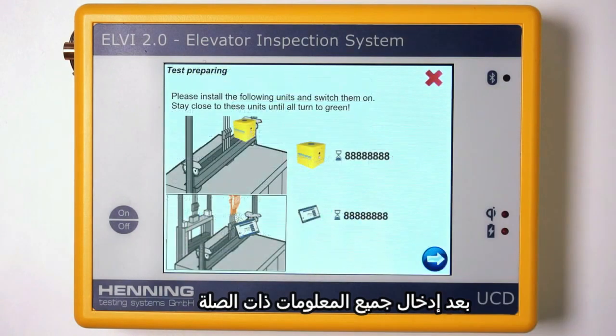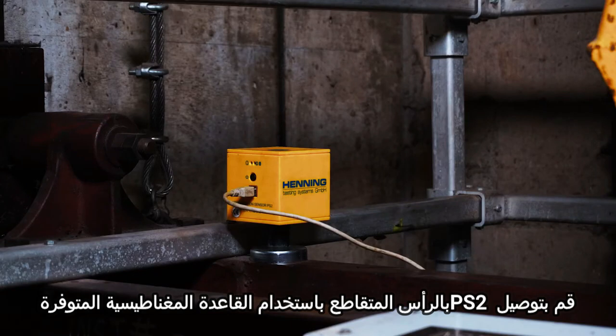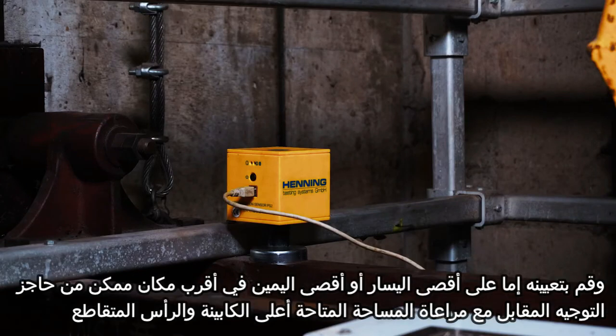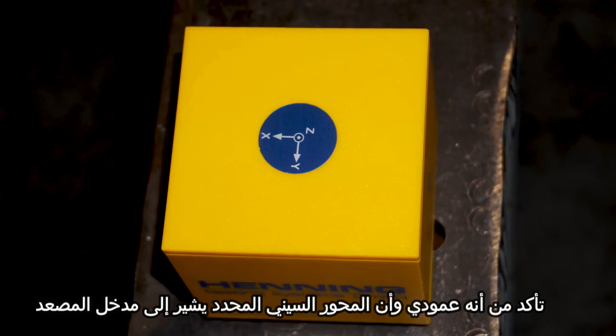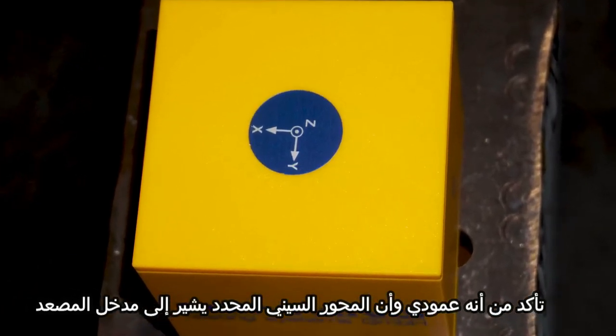After you've entered all relevant information, you'll be prompted to position the PS2 on top of the elevator car. Attach the PS2 to the crosshead using the magnetic base provided and set it either on the far left or far right as close as possible to the corresponding guide rail given the available car top and crosshead space. Ensure that it is vertical and the marked X-axis points to the elevator entrance.